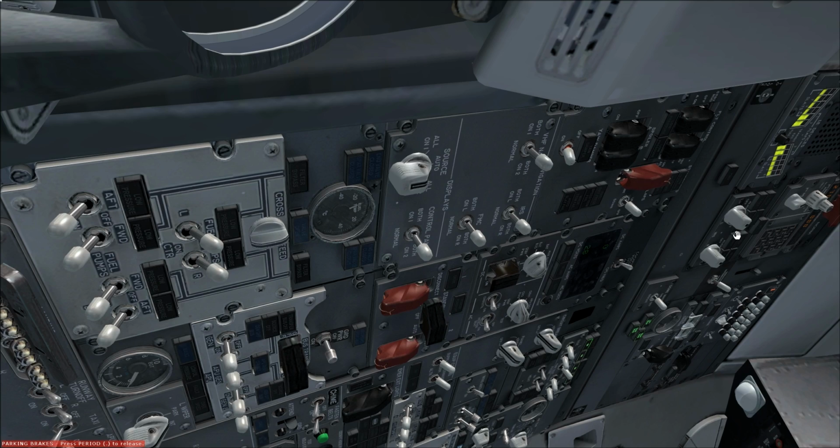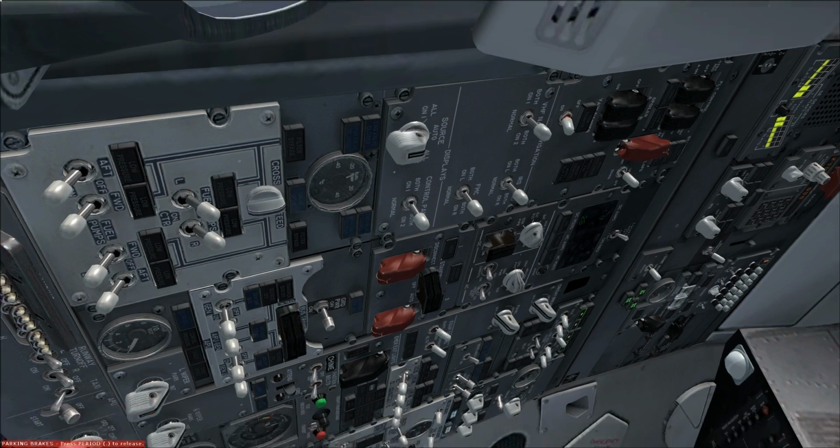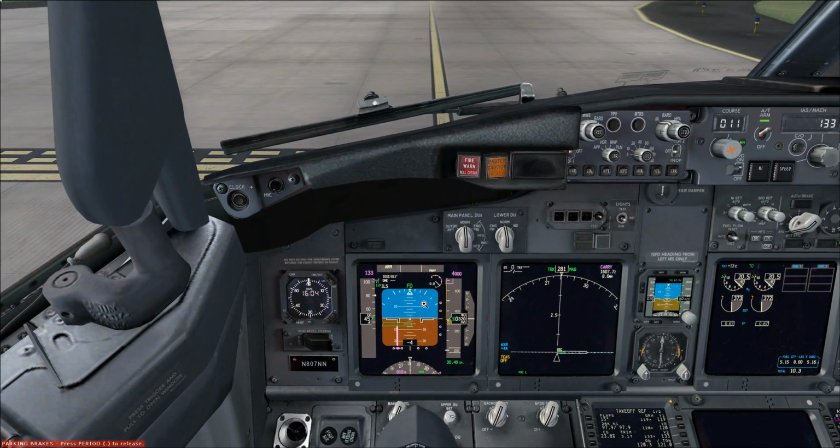And when that's detected, you'll get a two-toned aural siren, as well as an aural "wind shear, wind shear, wind shear." And it usually gives you visual cues on the nav display, and I think the PFD also, at which time you must use the wind shear escape maneuver and follow the flight director commands if you are flying manually.